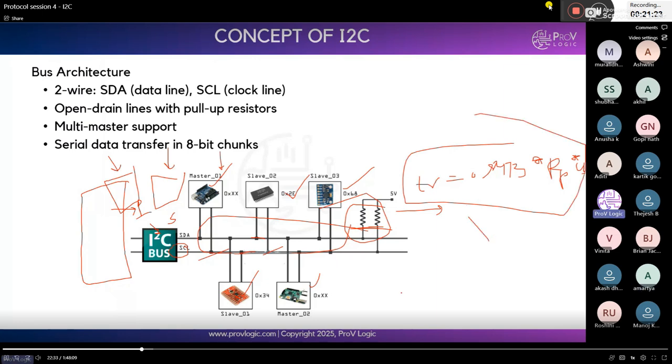But it is better if you have understanding, so whenever the question arises in an interview, at least you can remember the concept and tell it. Because of pull-up resistors, in the I2C protocol we are using different modes like fast mode, ultra fast mode. So how it is calculated is through the resistors. Whenever we are scaling the resistors, the rise time changes, and automatically the speed mode will be increased. Okay, so this is the I2C concept.